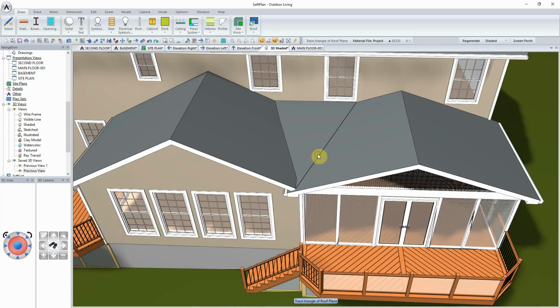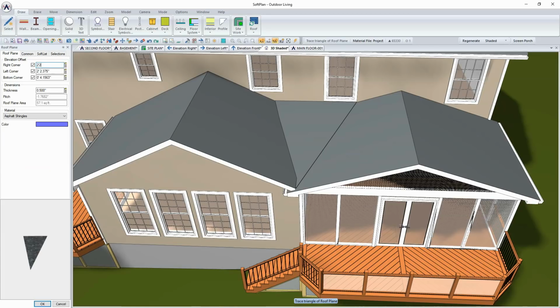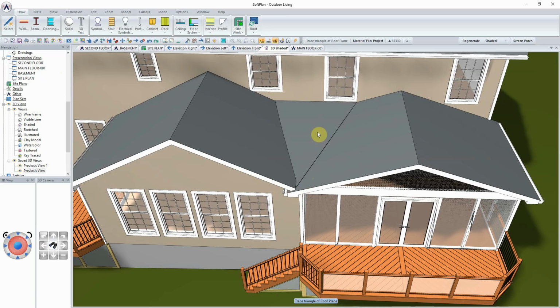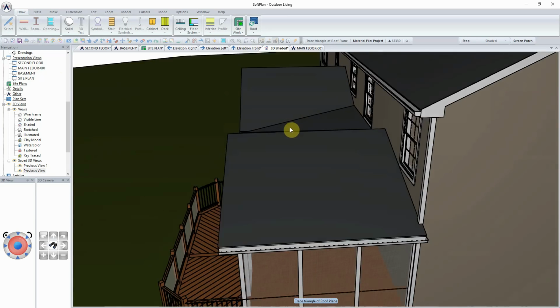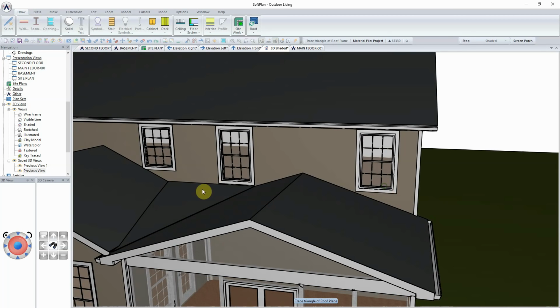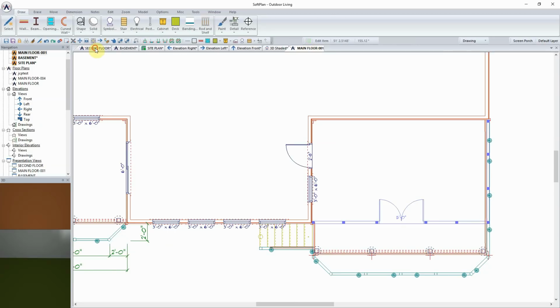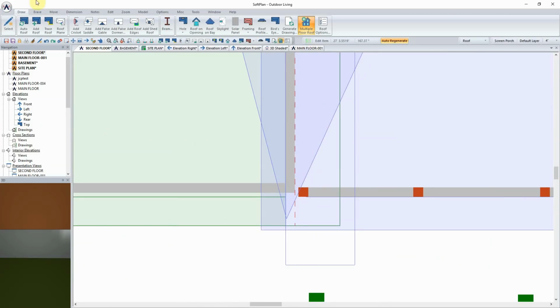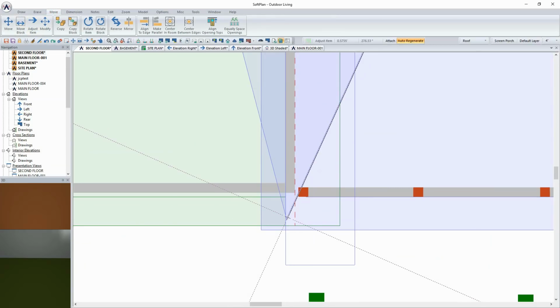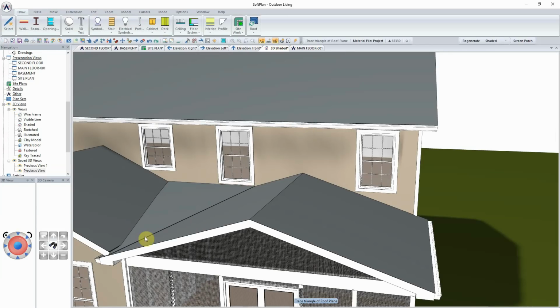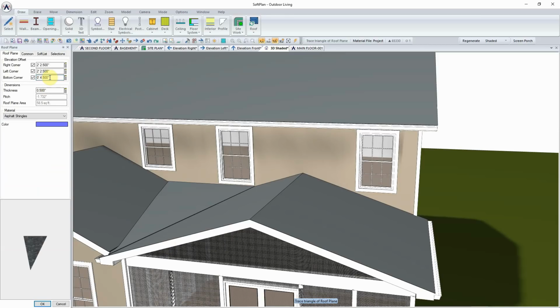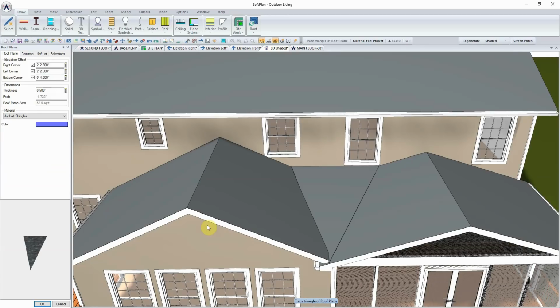This roof plane can be edited, and you can modify the actual height for exact dimensions, because right now I've just simply sketched it in. I can even change the height or the elevation on this as well. As we look at this roof here, we can see now we've got our larger roof on the screened-in porch. We also have our roof that we're going to shed in here. This can be completely adjusted from within the second floor plan. Using the adjust command, which is just move and adjust, I can pick the endpoint and drag it down to where I want the roof plane to run, so that we get the proper runoff. I was playing with the dimensions, so I'll edit this to be something that allows for a better slope on that, and we now have the roof setting.